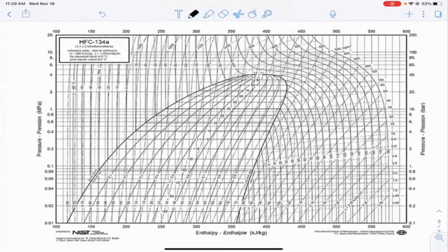Okay, so just like in the previous problem, we were told the two operating temperatures. We were told that the evaporator operates at -6 degrees C, and the condenser operates at 26 degrees C. And so what I'm going to do then is find A and C based on those conditions. Actually, Tamara brought up a really good point, that here's the saturation line, and that's all vapor. And on the line, that's all saturated liquid. I'm sorry if that's actually not so easy to read.